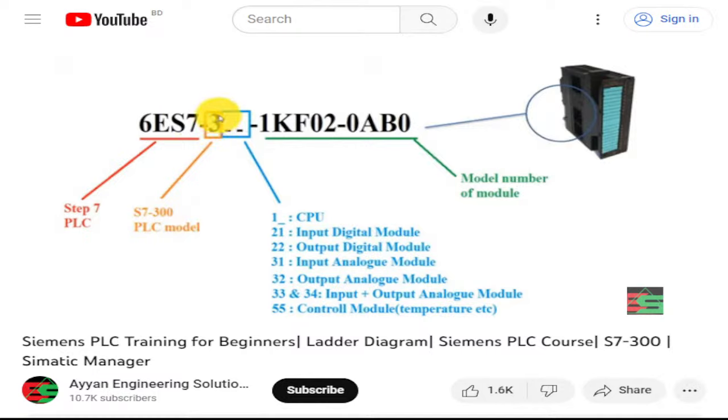Okay, this is S7-300 PLC model, and two more digits will be here. If it starts from 1, it will show CPU. If it starts from 2, this is the input digital module hardware. If 22, it means this is the output digital module.